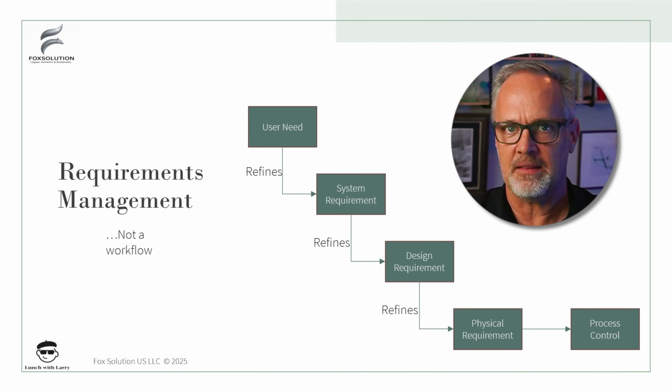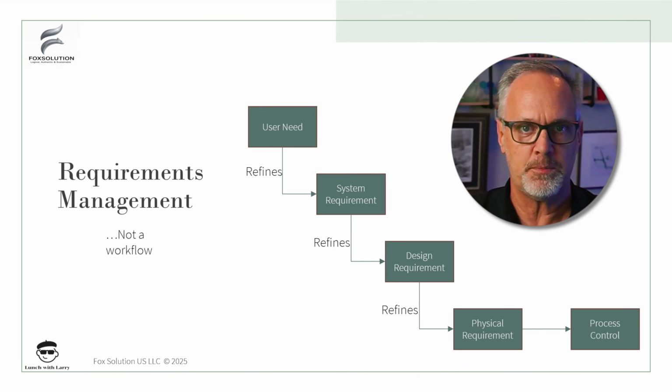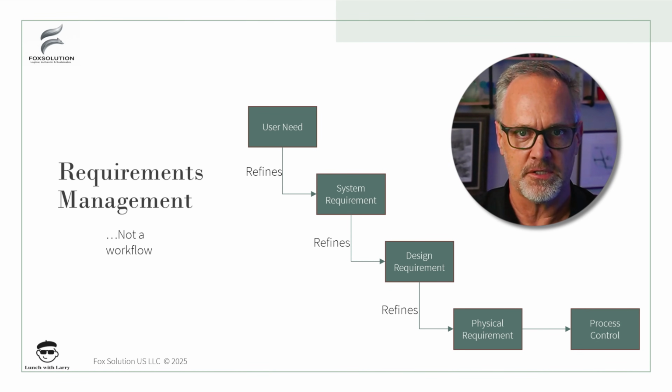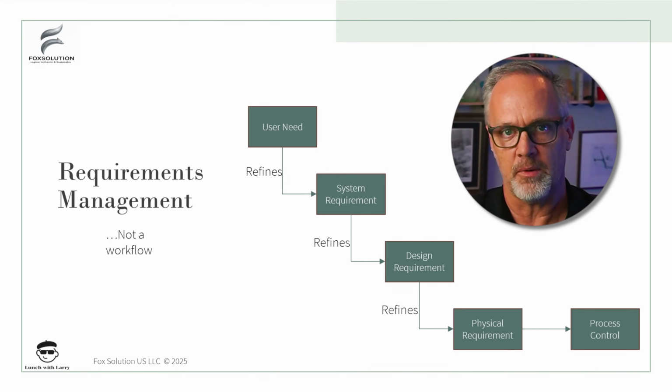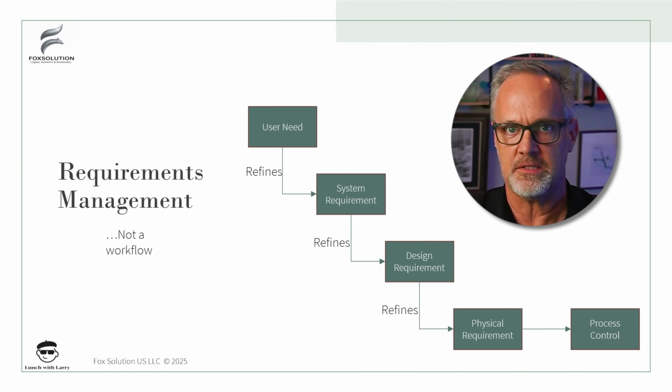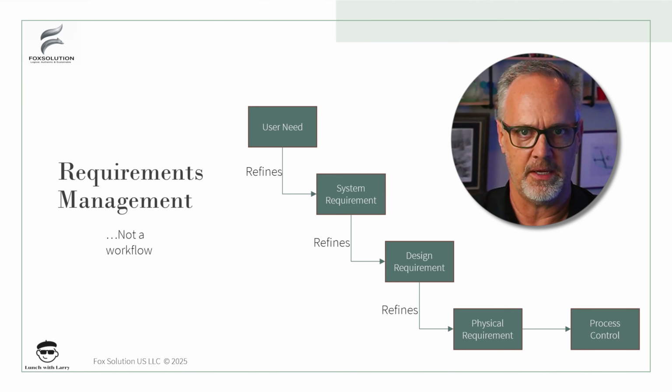It doesn't mean that I have to do user needs before system requirements or system requirements before physical requirements. These are really aspects of a data decomposition, and it won't be uncommon for us to bring in an internal standard that plugs in some design requirements that don't have system requirements attached to them. And we'll need to run that traceability up to user needs as we develop the design, but it doesn't mean I need to do one before the other or necessarily that I have to have these in place before I start doing any design work.